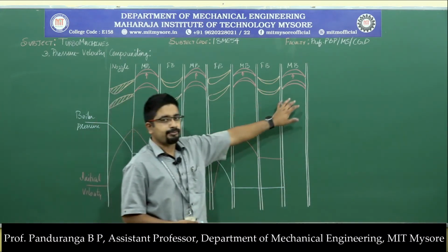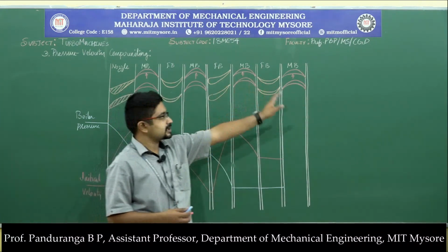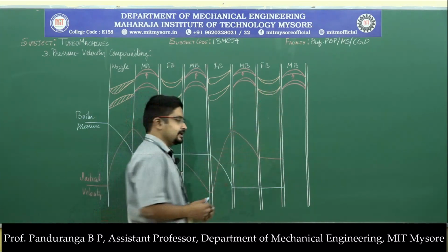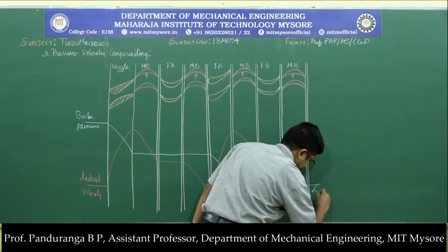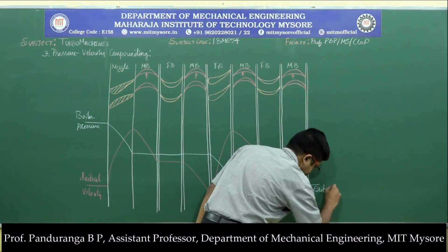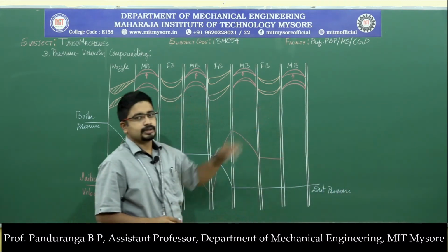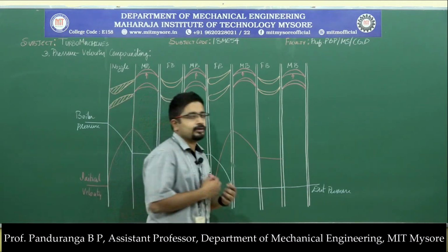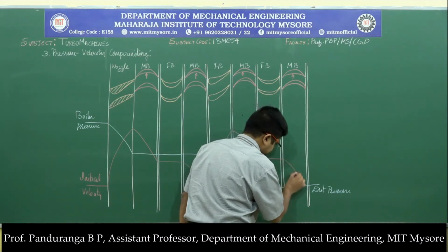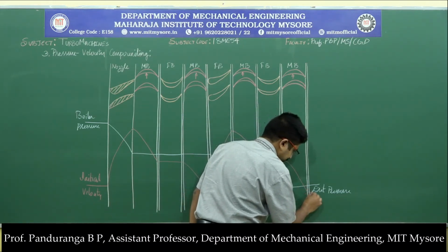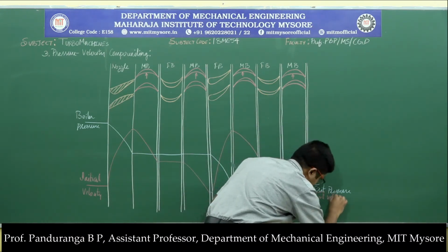Now the steam enters or passes through the last row of moving blade. So here the blade is symmetric, so there is no change in pressure energy. So the steam comes out of this stage with pressure equal to exit pressure, but since the blades are moving, it absorbs a certain amount of kinetic energy. So whatever the remaining kinetic energy, that will be absorbed by the moving blade. So it comes out with exit velocity.